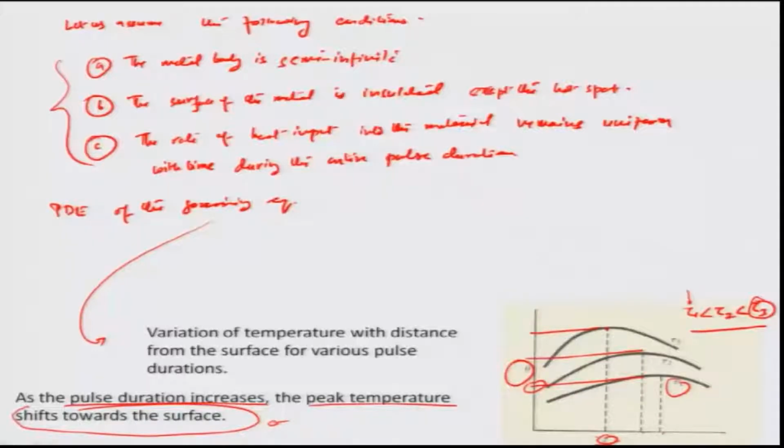Okay, so the depth will not be much of an issue there. But if it is a sudden impact process of a shorter duration, then the beam transparent layer would obviously be thicker, and it would have very little time to relax and conduct the heat in an outwardly manner, as if you are localizing the heat in a vapor pocket which has been created a few layers deep within the surface. So that is the reason why the maximum temperature, or the peak temperature, would be nearer to the surface for a higher duration beam or higher pulse duration than for a lower pulse duration.